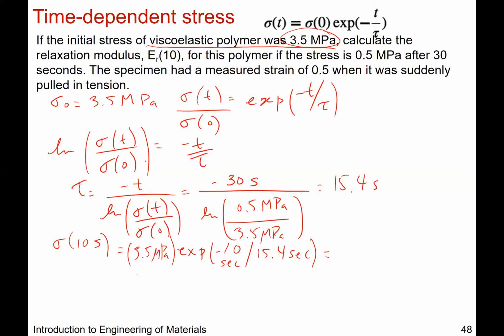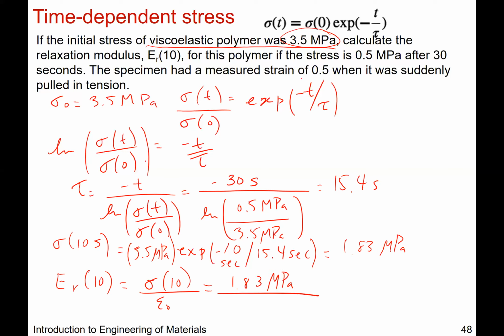If I solve this, I get 1.83 MPa as the stress after 10 seconds. And so then I can calculate the relaxation modulus. The measured strain instantaneously when it was pulled in tension is 0.5. And so basically I'm just doubling.